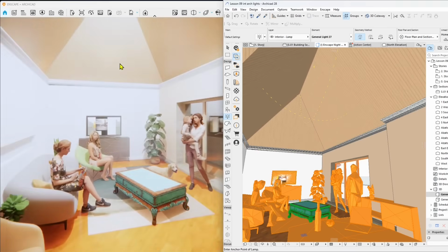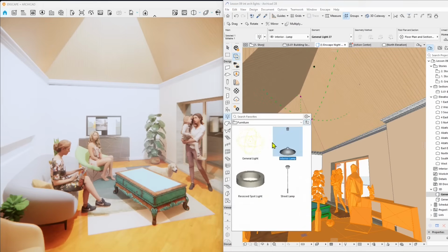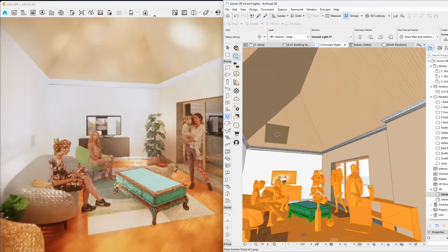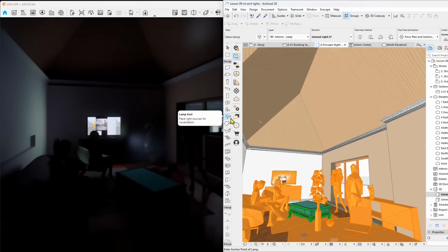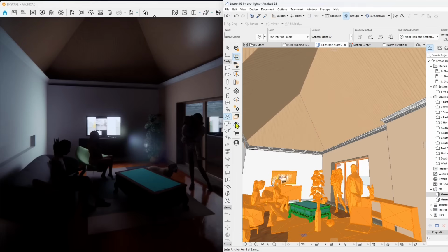So you can see here, I put a light, an OmniLight. This is a spherical omnidirectional light that projects photons and shadows in every direction. And we can see there the shadows and the intensity also of this light, which is kind of too much. We're going to delete it with the delete key. And so that's the basic one that we're going to see.